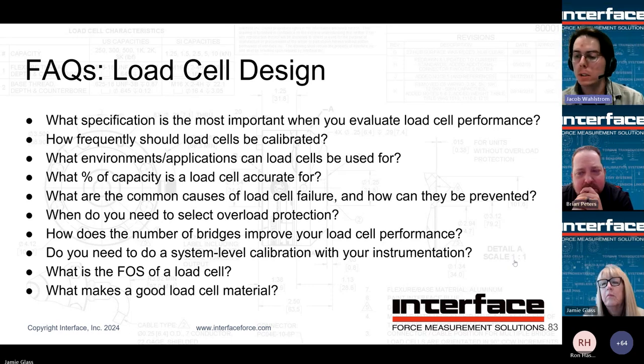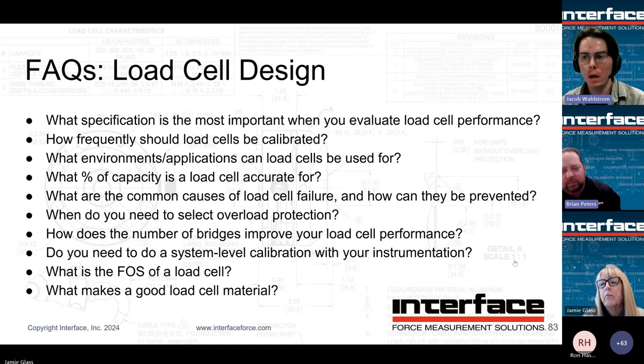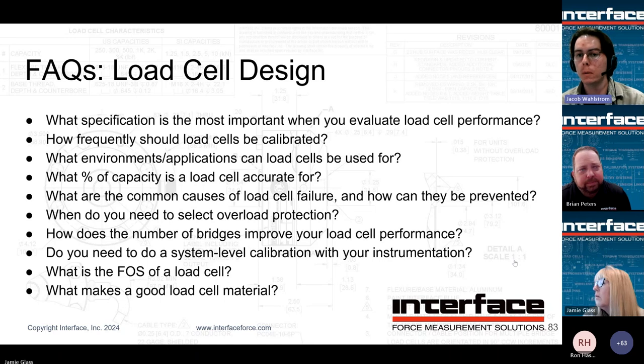Yes. I also would like to point out, is it from 0C to 170C, or is it a 170C spread? Because if it's an aluminum load cell, it could be going above the rated operating range. Which basically means the aluminum could be tempering and the material properties changing. Or gauges separating from the flexure.